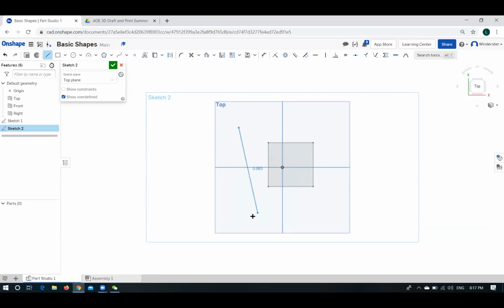You can either drag and drop by holding the mouse button, or you can make the first point and let go of the button. It'll do the drag itself. To finish, when you don't want to draw another line anymore, right click and it says escape line. Or you can use the escape button, the same thing.